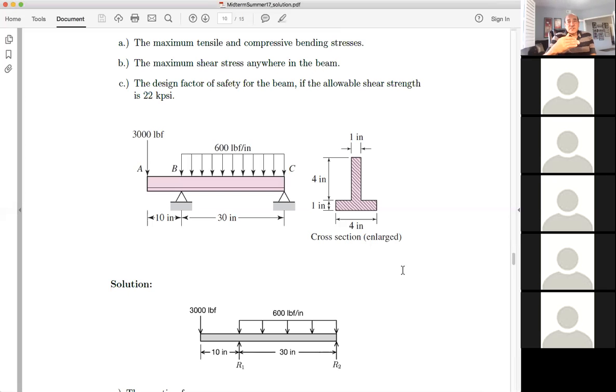shear forces, because part of the failure is going to be maximum shear, and the maximum shear is not the transverse shear. It is a combination of the transverse shear and the normal stress resulting from bending, right? Like we did in the shaft. So we have to get the shear distribution and find out where is the maximum shear.